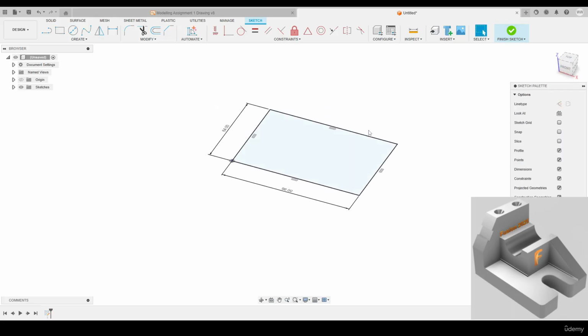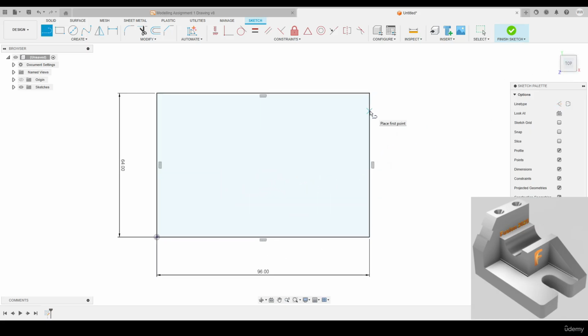Okay, that's looking good. Let's continue with the line tool, and we can input this slot feature just here. Go back to the top view. I'm just going to draw this in anywhere for the time being and then position that more accurately later. So that's got a dimension of 20 mil. I'm going to left click once there, hold down the left mouse button, and drag out an arc, let's say somewhere here, bring that back to the start line. Move that dimension out the way.